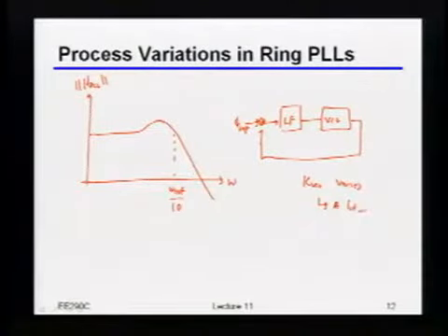Okay? Well, if the KVCO can vary quite a bit, what's going to happen, for example, if the KVCO got larger and I set my nominal loop bandwidth to be 1/10 of the reference frequency? What's going to happen? Want to reduce? Or reduce? If I increase the KVCO? Remember, you can be unstable.